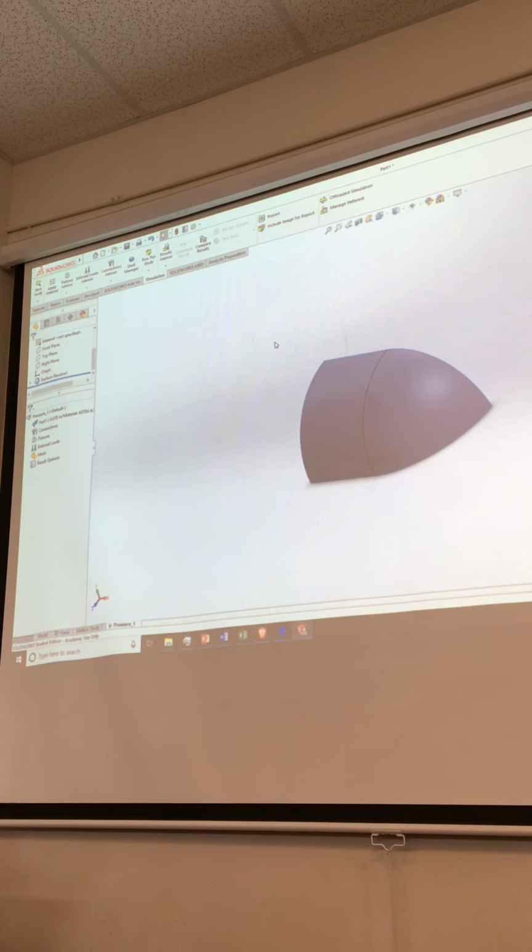Now, which one do you wanna do? Which one do we think is gonna be easier? Thin shell analysis. Thin shell analysis is gonna be a lot easier, right? Because a uniform stress assumption makes life a whole heck of a lot easier. We don't have to do some sort of gradient and figure what the inside and the outside are and all the rest of that sort of stuff, right? When it's uniform, then stresses are the same everywhere.